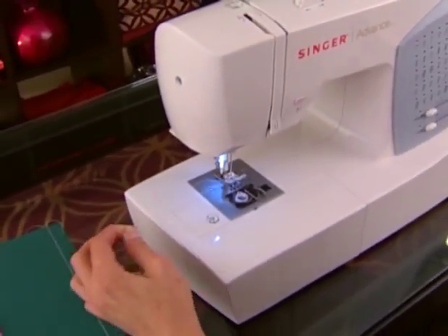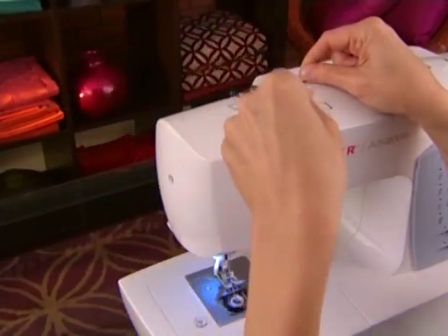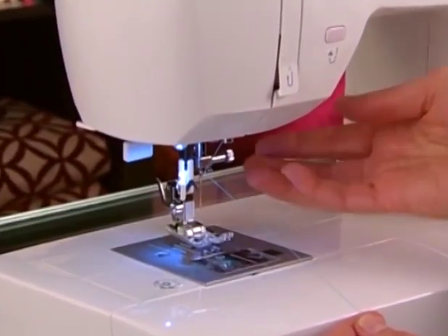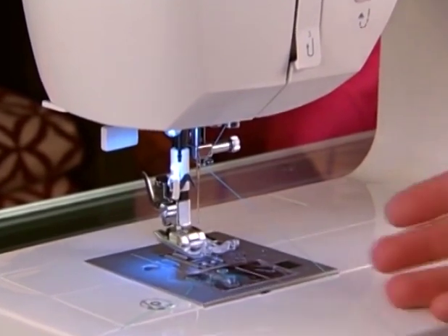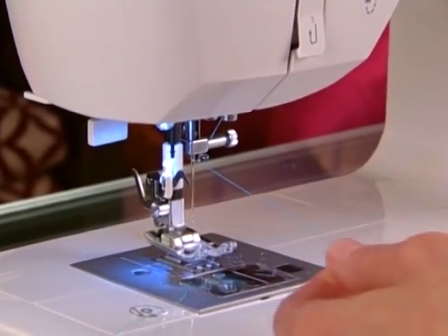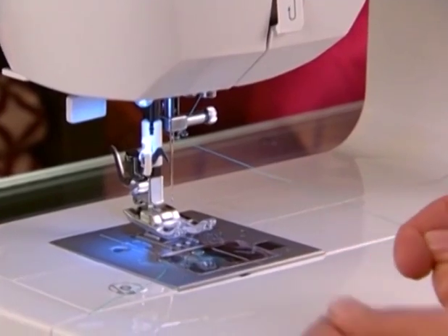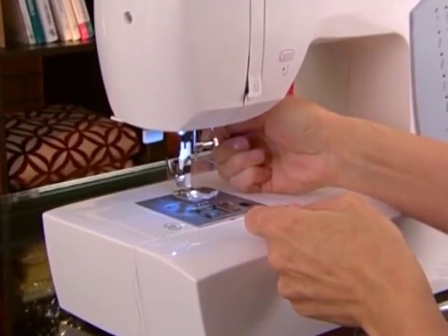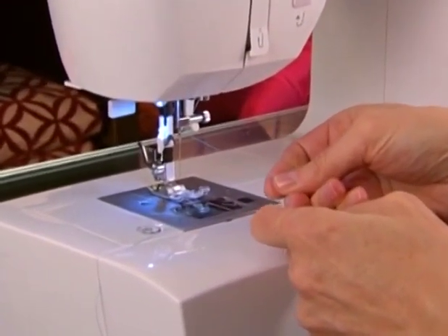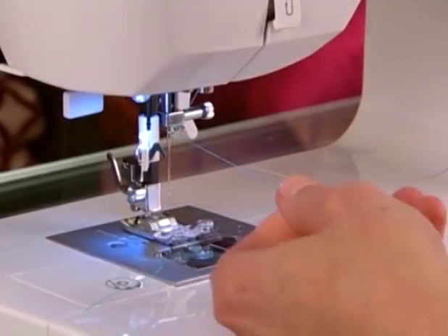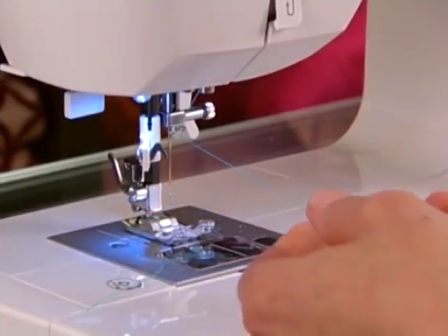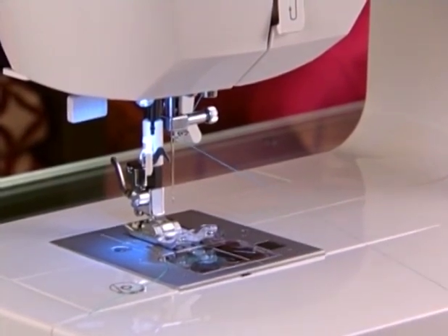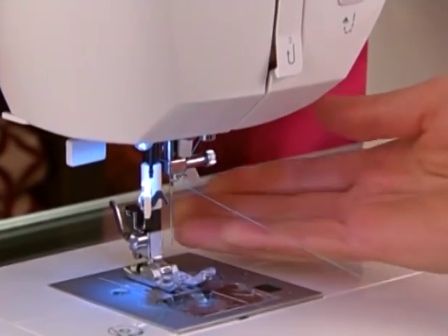To make sure you have threaded the machine correctly, try this simple test. Leave the needle unthreaded and the presser foot up. Pull the upper thread toward you. It should pull freely. Now, put the presser foot lifter down and try pulling the needle thread. It should resist the pulling. If you are still able to pull the upper thread freely when the presser foot is down, this is an indication that the tension is not correctly threaded.